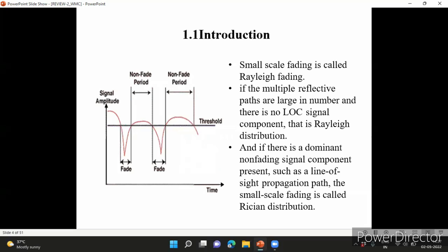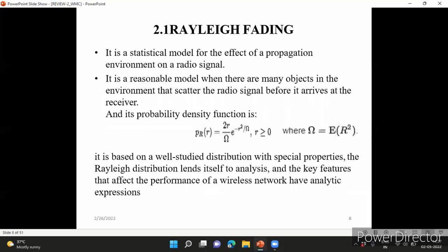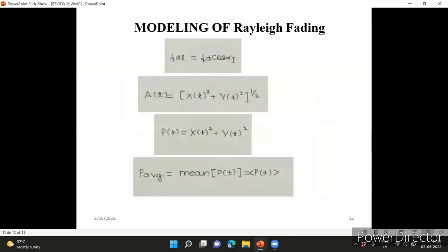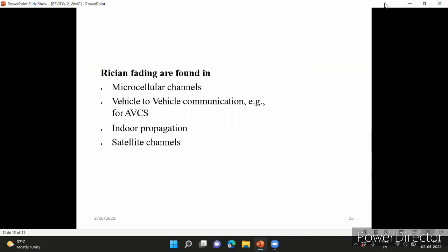Flat fading is a form of multipath fading which affects all the frequencies across a given channel either equally or almost equally. When flat multipath fading is experienced, the signal will just change in amplitude, rising and falling over a period of time or with movement from one position to another. So that's all about the introduction part, where we discussed what Rayleigh fading is and the modeling of Rayleigh fading. Now we will move to the simulation part, which will be described by Anshuman.